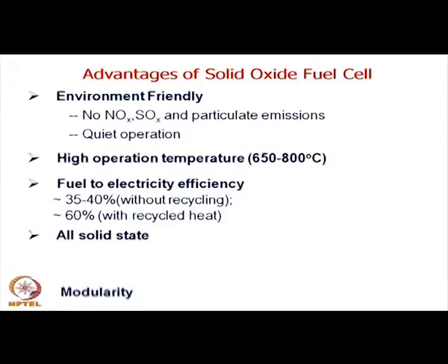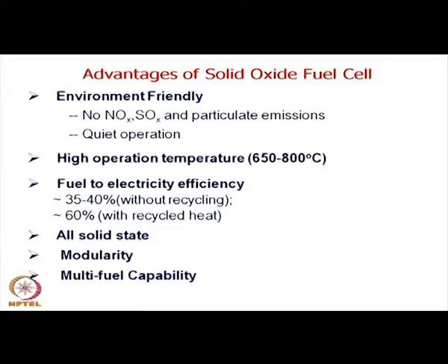It is all solid state, that is again an advantage. The other advantage is modularity. That is true of course for any kind of fuel cell, because a large capacity can be achieved by adding a few modules. So, there is modularity. You do not need to have a very large capacity plant all the time. You can have a few kilowatts up to megawatts, depending on the necessity, one can add different modules and enhance the capacity. Multi-fuel capability is once again a very important advantage, particularly for the solid oxide fuel cell.